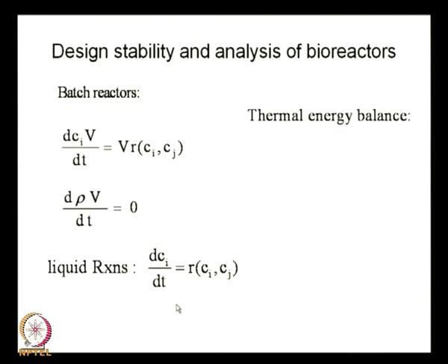And then you can add in a thermal energy balance if you want, which is if the temperature of the system is changing appreciably. Typically it does not change appreciably, the reason being there is a range of temperature within which the system has to be maintained, and you try to maintain it within a small range. Within that small range the changes are not large, because these growth reactions do not have a very high activation energy, and the heat of reaction is not really very high.